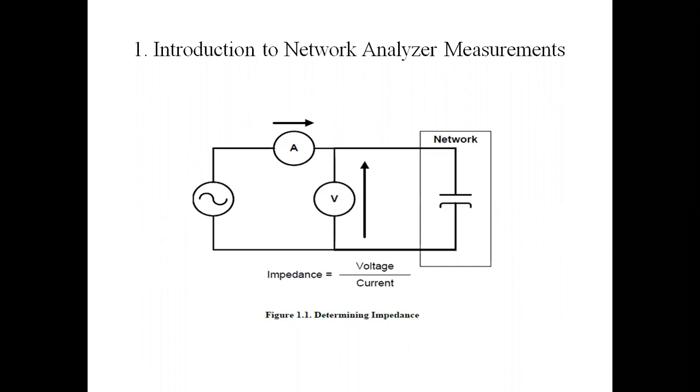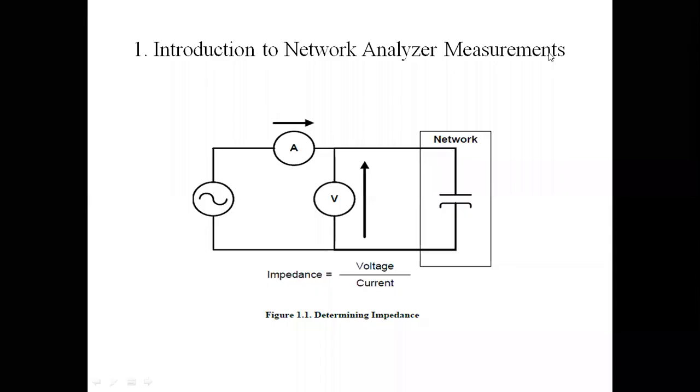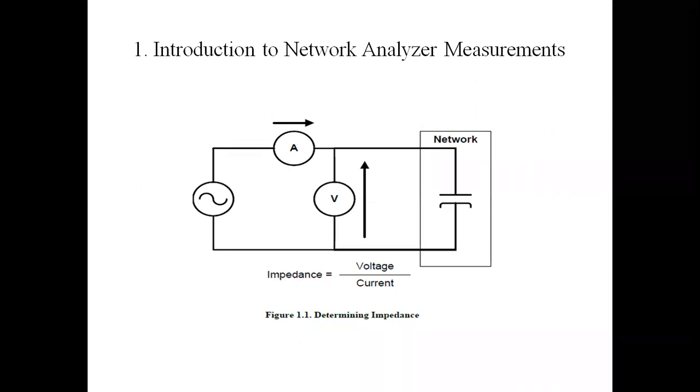At RF and microwave frequencies, the measurements of voltage and current become more complex. So the VNA uses a more complex design to measure the incident and reflected waves. In many ways, the VNA marries the principle of basic impedance measurement with hardware appropriate for microwave frequencies. When using the VNA to measure the impedance or the reflection factor, a sine generator stimulates a device under test.